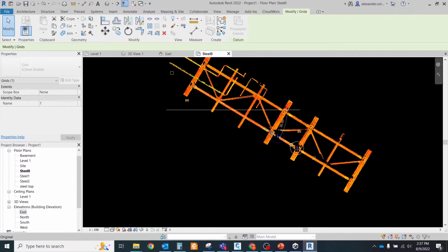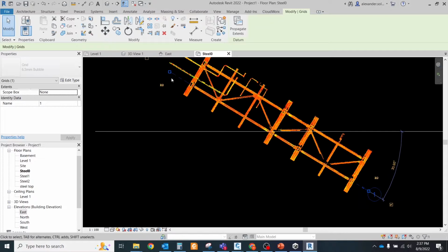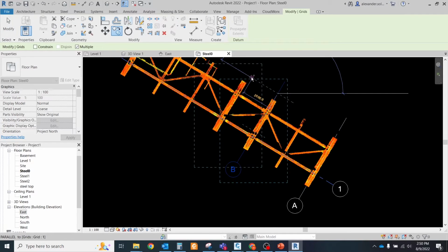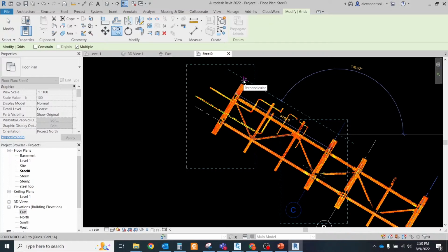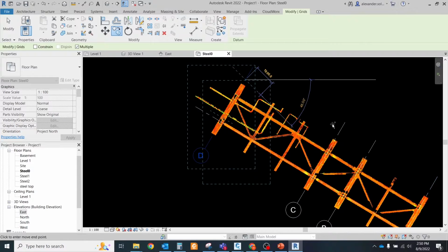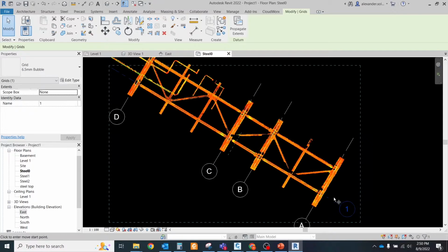This method can be used for some other applications as well. But in any case, it helps us to determine the direction of the axis. Once created, you can move the axis closer to the center manually. The GridLine tool works very well when you have a clean point cloud with the required elements that can be used to extract patches, but in many cases there are too many obstacles that prevent you from using it correctly.